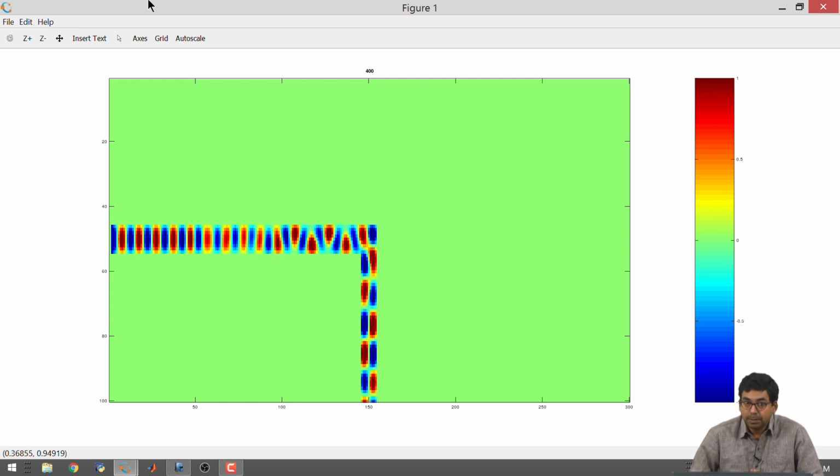Okay, now I noticed something that we have not seen or studied about before. All right. We have talked about positioning of the source to create different modes. We have also talked about the width of the waveguide that can support different modes, and in this particular case I had used a line source to excite this parallel plate waveguide. I assumed it to be single mode, but when I inserted a 90-degree bend, I noticed that the pattern that's coming in this 90-degree bend is very different from the pattern I was getting in the horizontal section.